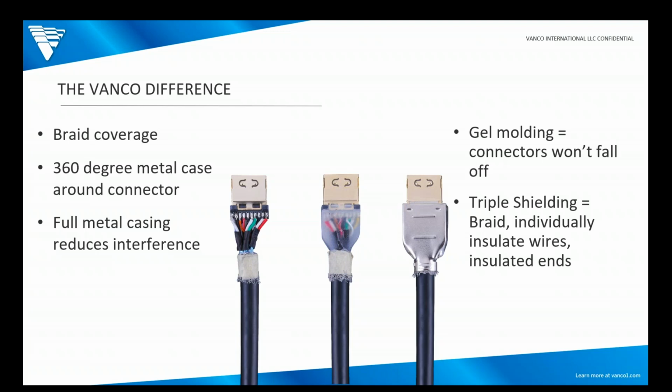Now, residential application, cable box to TV, not a big deal, okay? However, if you're working with a higher-end residential or even a commercial application with an AV receiver, or a splitter, or matrix unit, guess what? You'll have all of these HDMI connectors plugged in right next to each other, and you can and will have interference in the form of sparkling, snow, and I've seen it, blinking as well. So again, it really does matter in terms of the guts of the cable. We cover our cables from tip to tip in a nutshell.